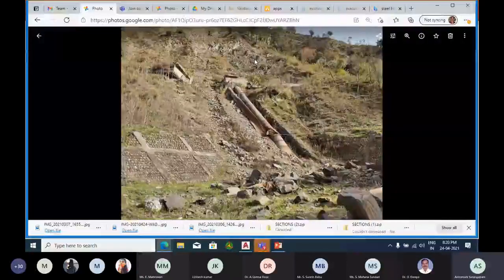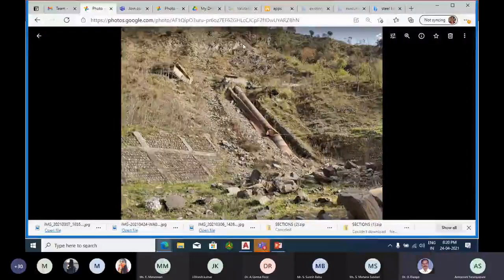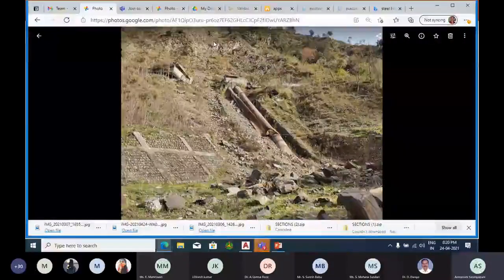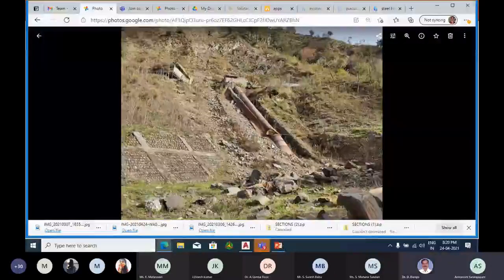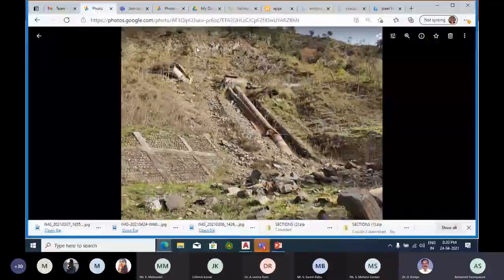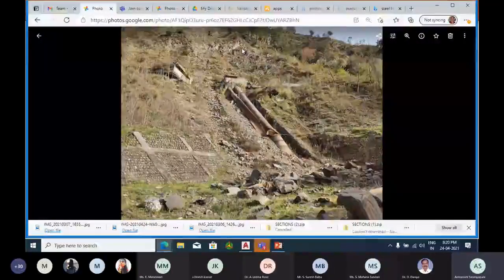So the length of my penstock is not going to affect; only the slope stability matters, because for laying this penstock, I have to disturb my parent hill. The hill was not originally like this. The hill was somewhat like this. These people excavated this to construct this penstock. They excavated this, so this failure happened from here and it started hitting, sir. So making the slope stable is the important thing. That will save my powerhouse. That will save my project in the longer term.